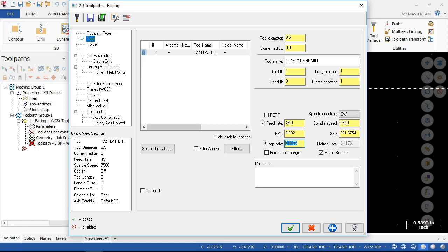Now we can be more aggressive. On a part that's 2.5 inches long, are we really ever getting to 45 inches a minute? No. It's debatable. Your acceleration and decel rates, you may see it on the control. It says it's doing 45, but realistically it's not. So if that's the case, then I'm better off staying at the lower and then making the adjustment as we go, as we see the results.